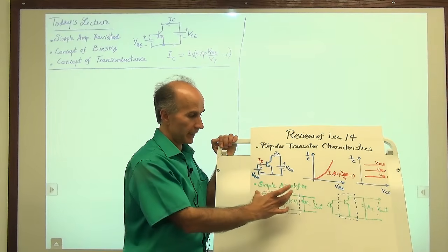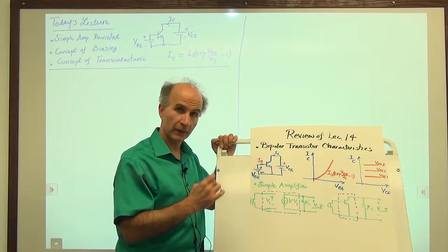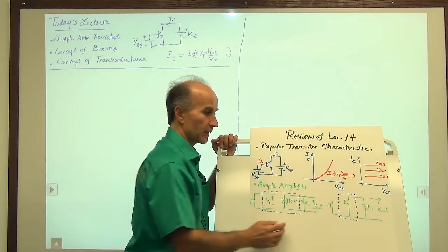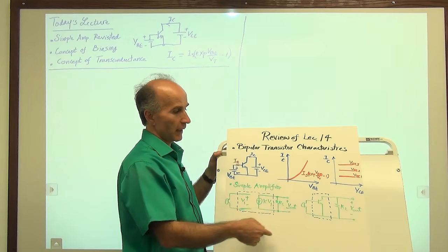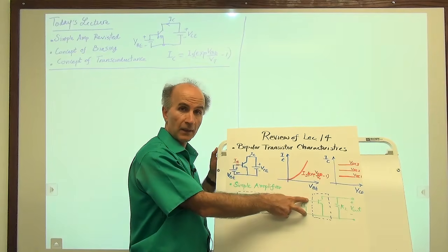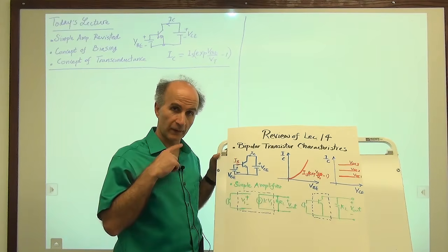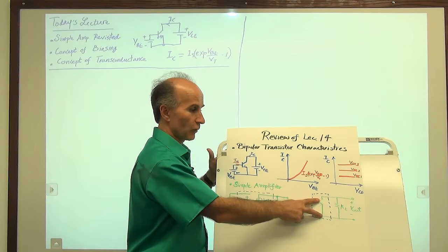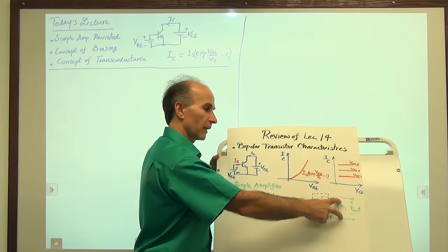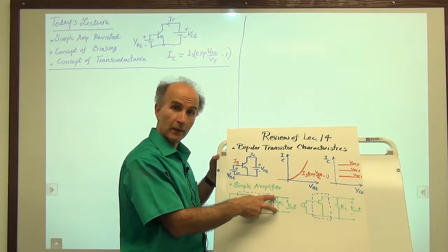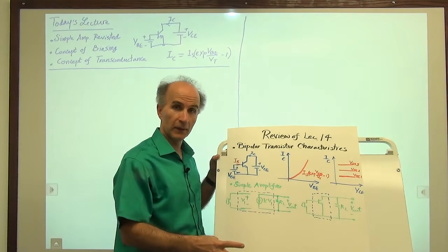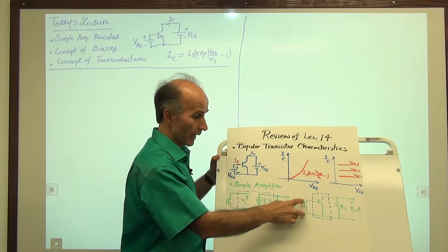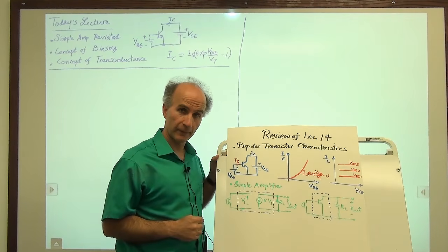So why don't we replace this voltage-dependent current source with a transistor? So we replace it like this, and what we expect is that if we connect some sort of signal here, let's say microphone signal, so the signal that's going to this microphone from my voice, and give it to this transistor and connect this resistor like before, we should have a voltage at this output that is greater in swings than what the microphone produces. And that's what we will call an amplifier.